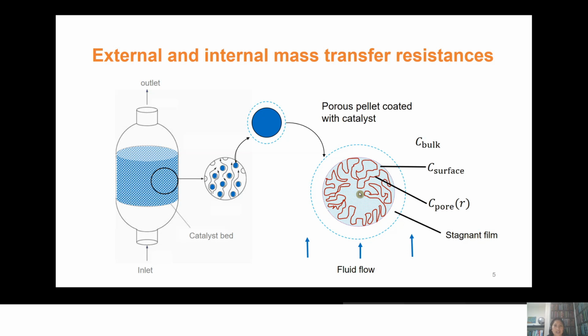So you have your molecular diffusion, which is collision between particles, between molecules, between species when they collide with each other. So that's molecular diffusion. Your species can hit the wall, so they can collide with the wall, and that's called Knudsen diffusion.